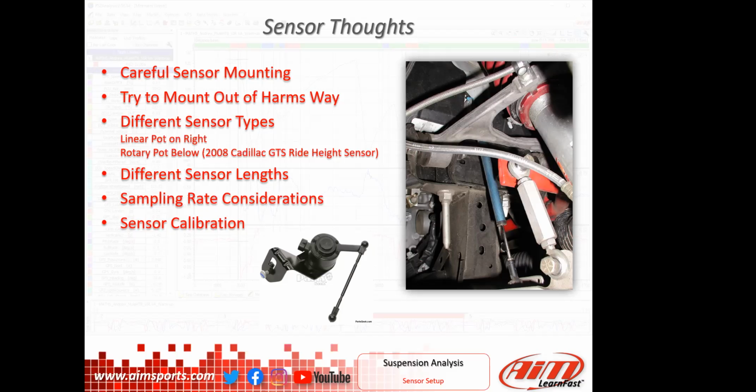What you have to do is sit down and think about what all of your different sensors are, how quickly that particular channel changes, and how fast you have to sample it in order to gather the information you need about it, right?